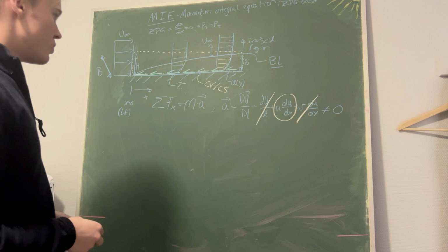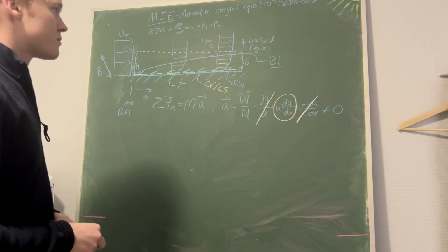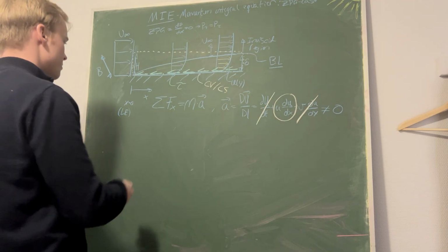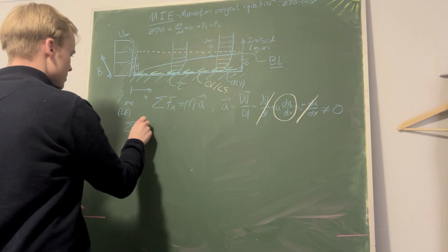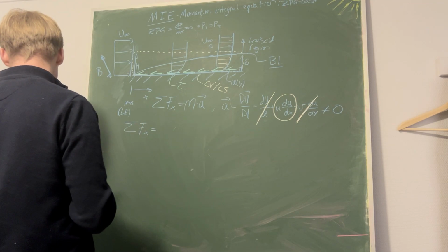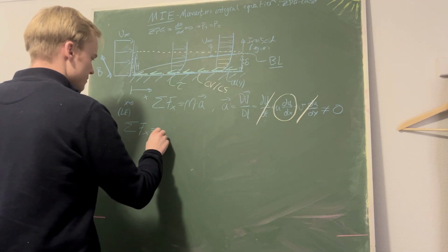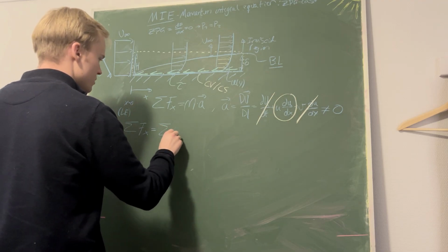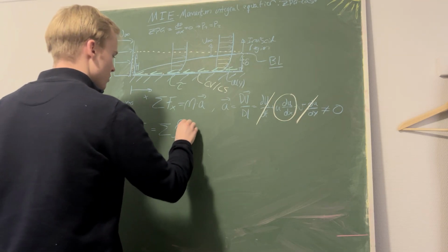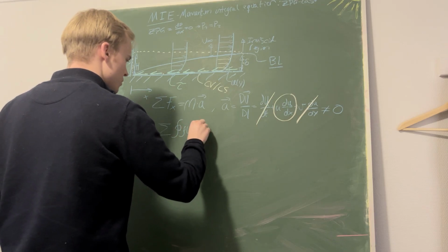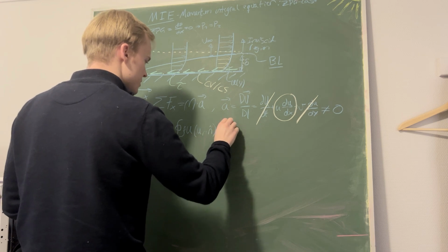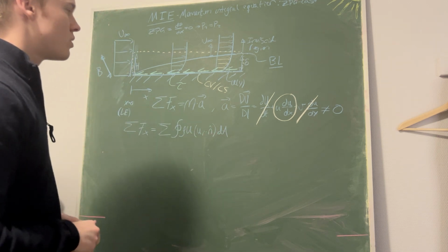And by that, we will use something called the linear momentum equation. So what that basically ends up being is, we have the sum of the forces in the x direction. That is going to be the surface integral of rho u, dotted with the normal vector, times dA, an infinitesimal small area.